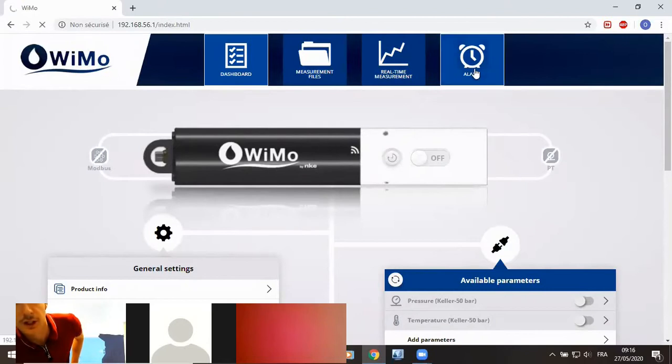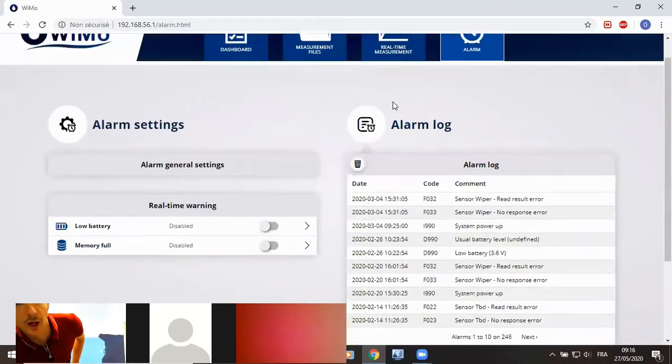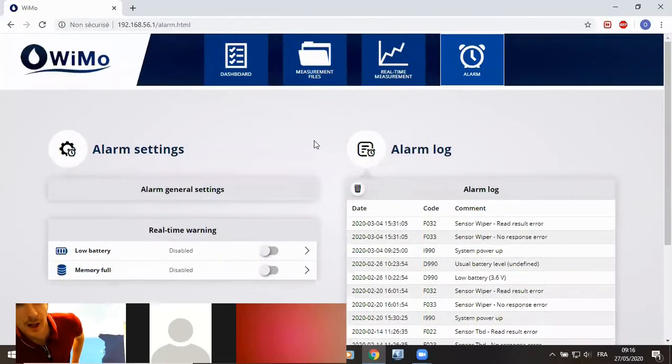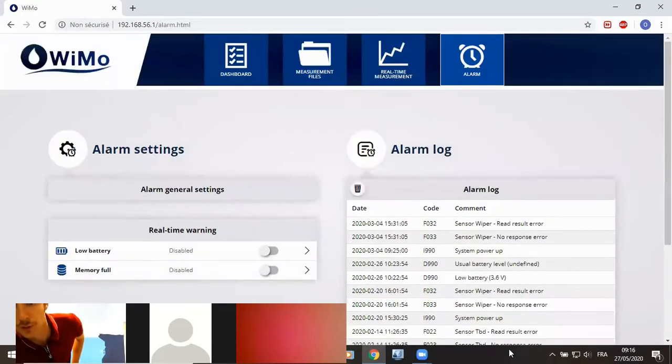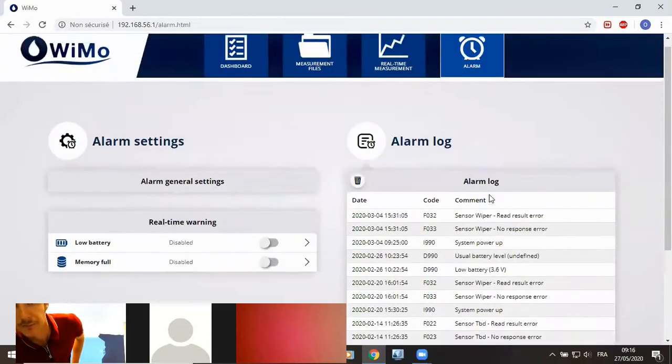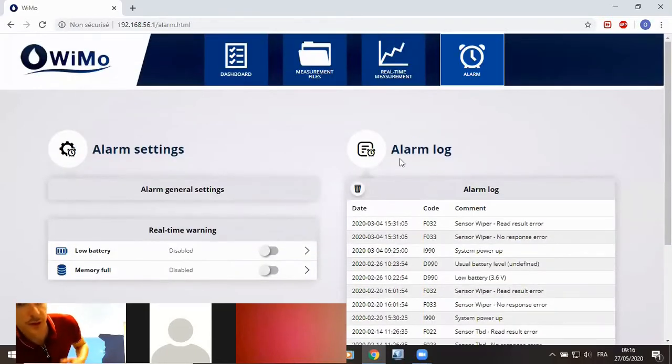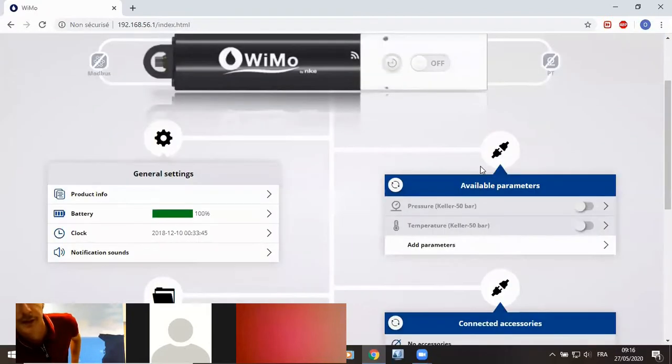And here it's a specific table called alarm, dedicated to help us with the response of the probe for long-term deployment. Typically, did something block the wiper? Is something going wrong? Do I have low battery, etc.? So you can select whether or not to log the key alarm information, and this is more dedicated to long-term deployment with the transmission module that I will show you afterwards.